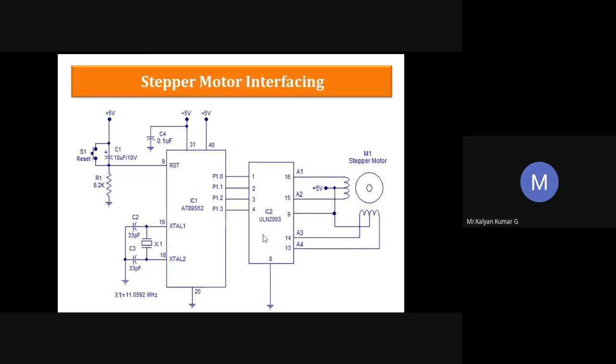At least you would have typed the part number ULN2003 and found what device it is. Fine, so we need a motor driver circuit. A motor driver IC is normally required, and it acts as the interface between your controller and your motor.